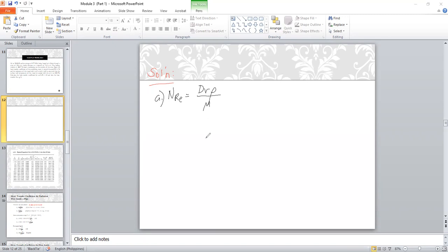So the first parameter, we need to check what we know, and of course we need to look for what is not given. So as for the diameter, do we know this already? Okay, the diameter is given. It's given a while ago as 25.4 mm. So velocity is also given. So that leaves us with the density and the mu.